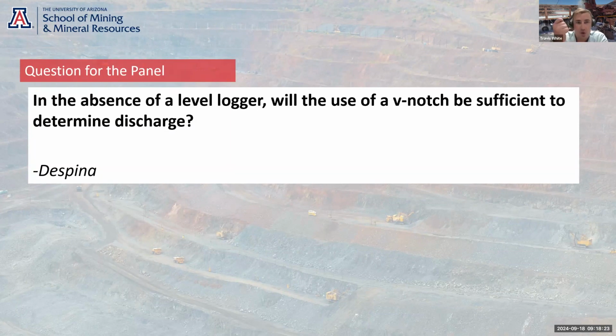And then when you develop the hole, so when you blow and flush all the drill cuttings, you do that as long as you practically can, and it's going to vary from site to site. It's the best sort of proxy for a reverse circulation airlift test, and you make sure that you get sustained flows. You can't install a level logger when you're using that kind of method. But ideally, what you would have in place is either the pilot hole nearby where you can put a level logger down, or a VWP already.